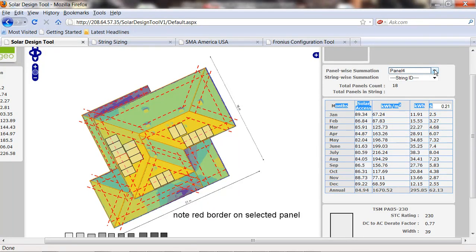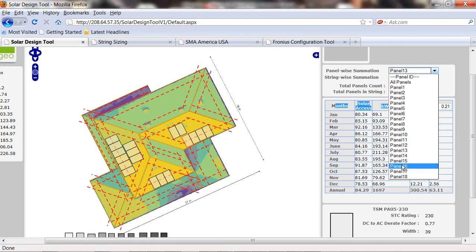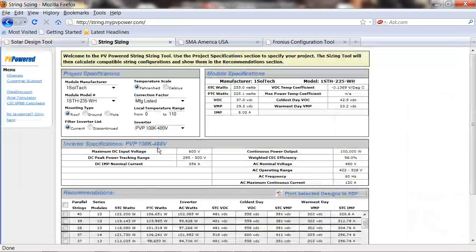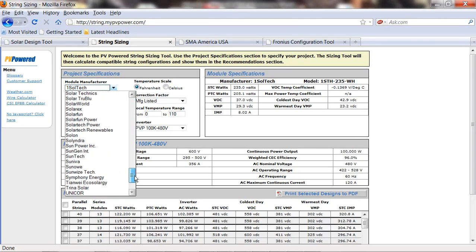And when we do add the panels to strings, we want to keep in mind that the performance will be based on a multiple of the weakest panel in the string. All of these capabilities and insights will help answer questions during the sales process. Questions regarding microinverters, power conditioners, SolarEdge inverting systems, conventional string inverters such as SMA, Fronius. Having the answers to questions and concerns immediately available will facilitate your sales process.